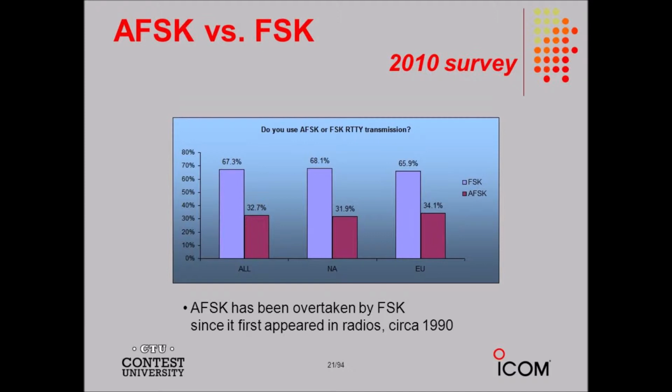Frequency shift keying. We can send digital data faster and with fewer errors than Morse code will allow if we use frequency shift keying, FSK. In some FSK systems, the carrier frequency shifts between mark and space conditions, usually by a few hundred hertz or less. In other systems, a two-tone audio frequency, AF, sine wave modulates the carrier, a mode known as audio frequency shift keying, AFSK.